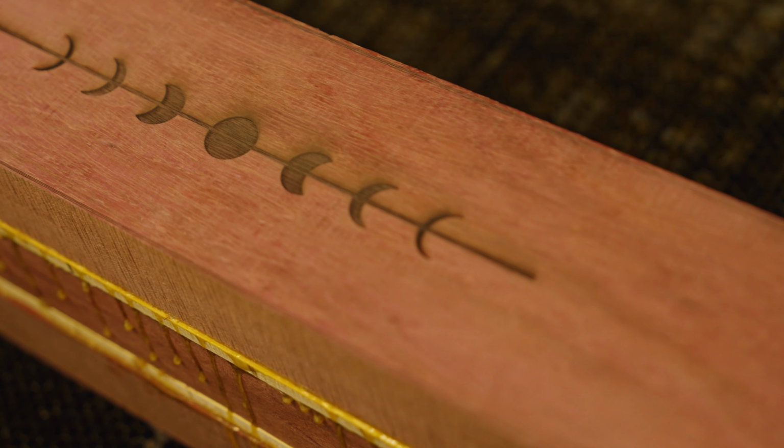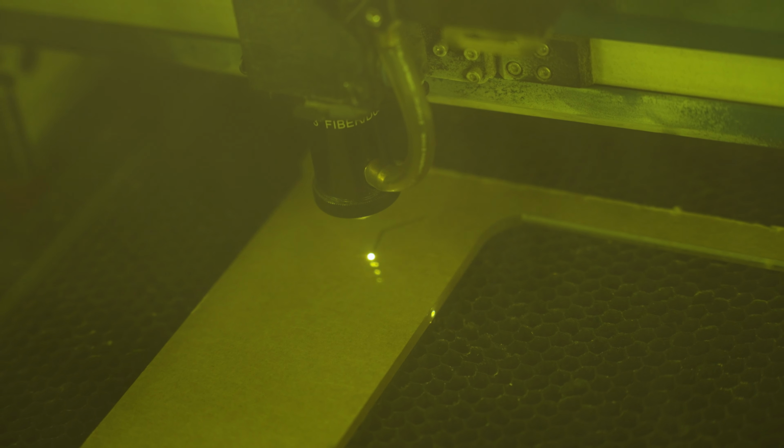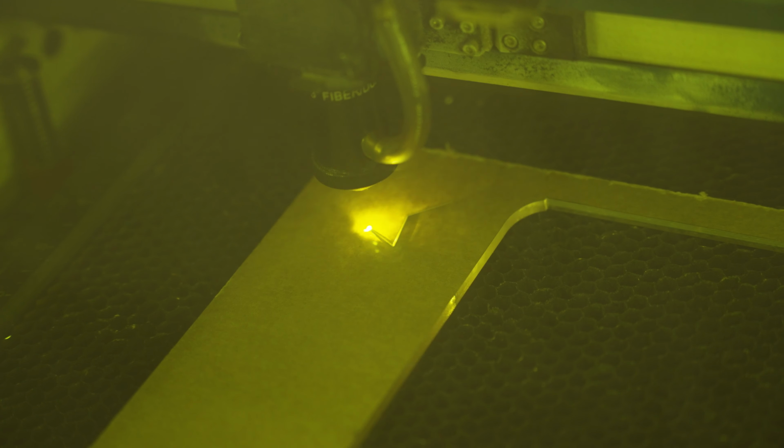Our machines can work in two modes, engraving mode and vector mode. In engraving mode, the laser moves methodically back and forth one line at a time, turning the laser on and off as needed to etch the desired shape in the same way an inkjet printer might deposit ink. We typically use this mode to create shallow engravings on the surface of the part. In vector mode, the laser precisely follows a path you have drawn, most commonly to cut a shape out from a larger piece of material. In both cases, we can vary the power and speed of the laser to indirectly adjust the depth of cut.